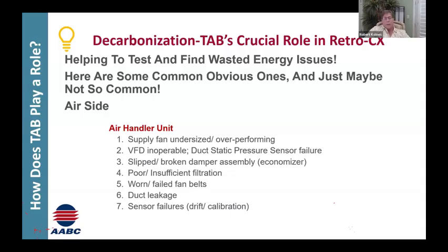Or how about where you find the filters are not being maintained, or they're being maintained but they're completely filthy, dirty. Your fan speed has to overcome that, so you start increasing your fan RPM. Or if the filters have completely failed and fallen right into the face of the hot water coil. For the Vegas market anyway, the heating coil is there first, upstream. All of that leads to wasted energy.